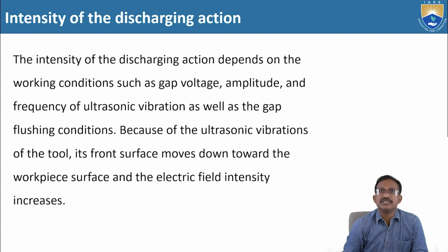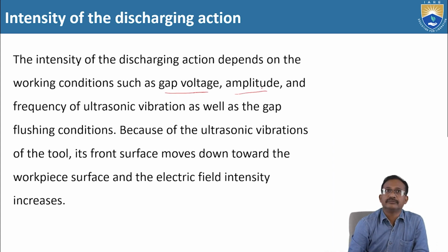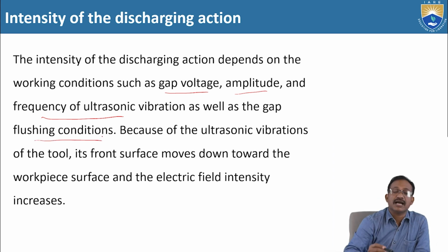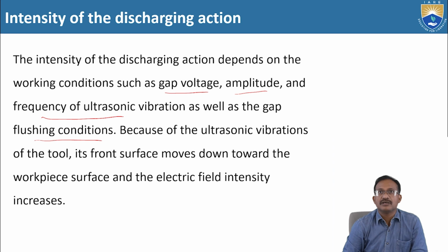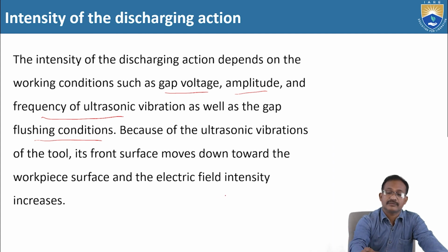The intensity of the discharging action depends on the working conditions such as gap voltage, amplitude, and frequency of ultrasonic vibration, as well as the gap flushing conditions. Because of the ultrasonic vibrations of the tool, its front surface moves down toward the workpiece surface and the electric field intensity increases.